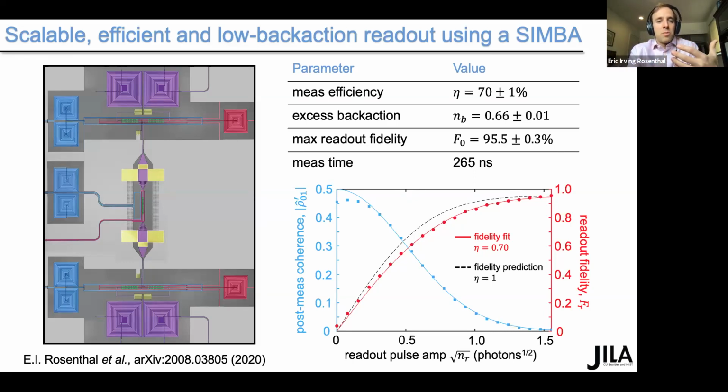It's maybe worth saying that this SIMBA is made with an optical lithography process at NIST, and the junctions are several micron wide junctions with silicon dioxide between them. These are very lossy junctions, so you can't make a good qubit on the same chip as our SIMBA in our fab process. But I do think wire bonding two chips together would have worked pretty well.